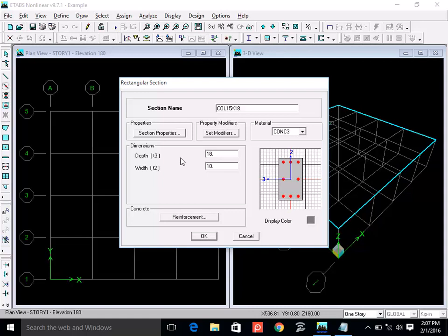For example, in this beam, 1 is longitudinal, axial. 2 and 3 are like this. 2 and 3 may be vertical, I'm not sure. For a column, this axis is 1. Now notice the change in dimension. For example, right here, you don't know what is T3. You don't know whether T3 means the dimension parallel to axis number 3, which is this one, or it is perpendicular to axis number 3. You don't know, right? So you need to change something.